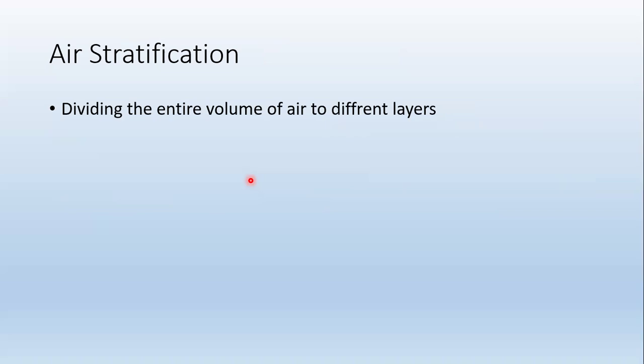So the working, especially in the cases of theaters, even these double ceiling height areas, in those spaces, generally they will go with some kind of jet or nozzle diffuser, or even eyeball diffusers. These eyeball diffusers are placed at a certain height from the floor level itself, isn't it? Like I told you, for double height ceiling levels, they will be implementing these kinds of eyeball diffusers. However, if the height is too high, that's not a problem.